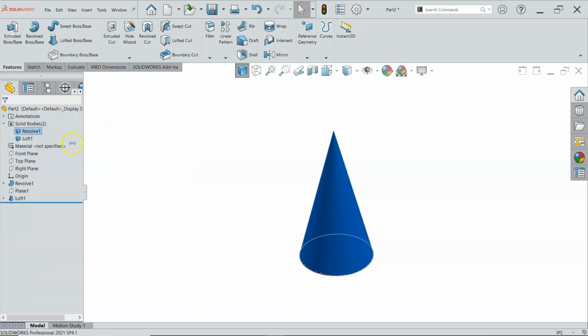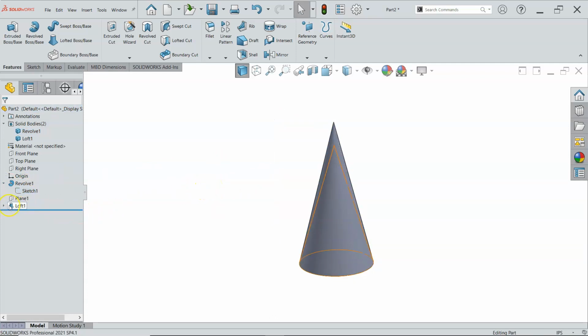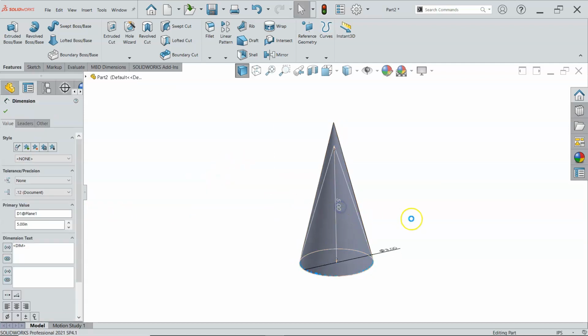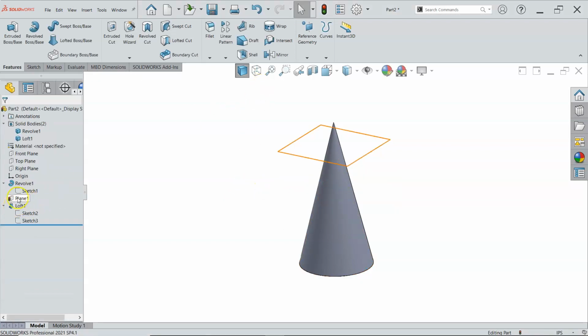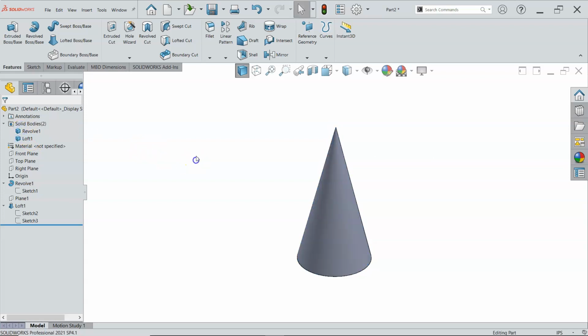And then we'll do the same thing. I will show the geometry. See what I did to the, oh, I went 6 inches. So that's why it looked a little bit different. That very quick view. So if I change the offset of the plane by double clicking on the plane and then on its value, again I will see the little stoplight, so I need to rebuild. And now when I highlight the loft and I highlight the revolve, I'll see similar geometry.